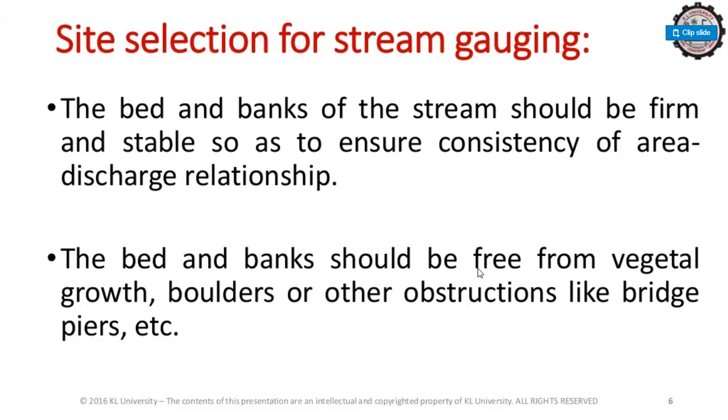The shifting control may be due to the effects of changing channel scour and silt in alluvial streams, backwater, rapidly changing stage in the stream, unsteady flow conditions, variable channel storage, and aquatic vegetation.